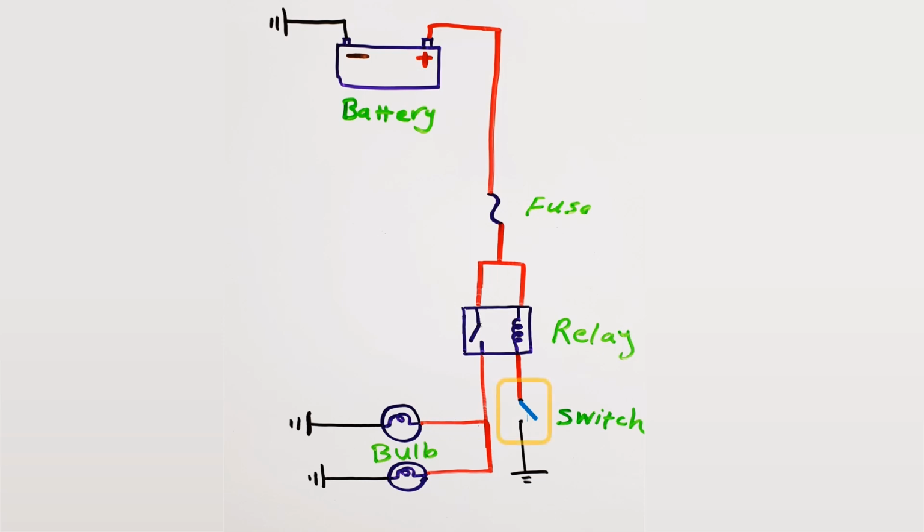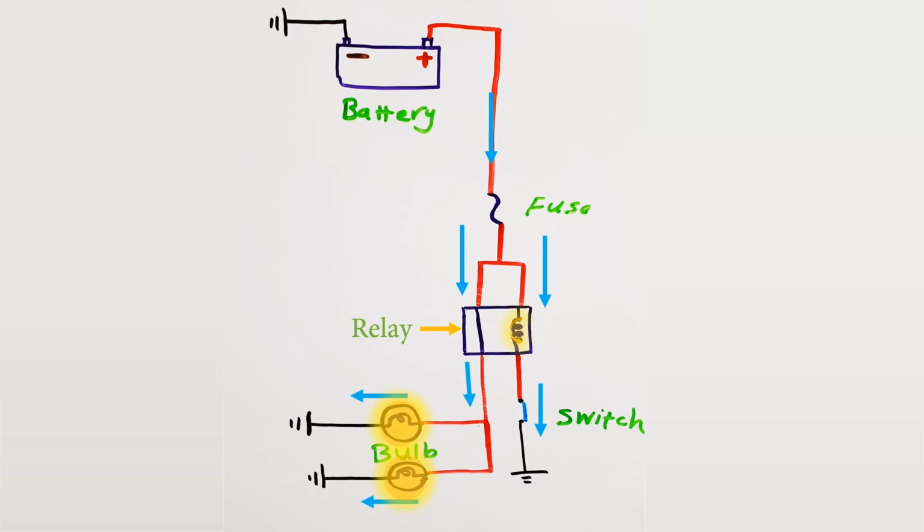Now, to solve these problems, we can isolate the switch from the main circuit and use thin wires to connect that to a relay. When this relay is activated by the switch, the coil inside makes a magnetic field that connects an internal switch for the main circuit. So this relay makes our design more optimum and efficient, and our circuit in simplest form turns into this configuration.